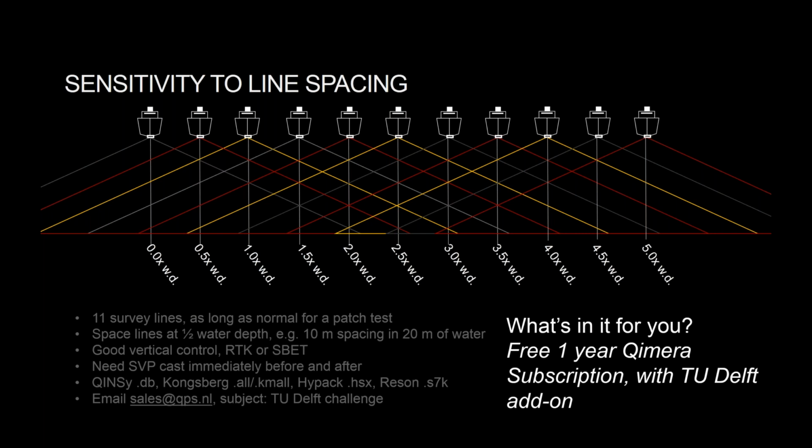Great. And so another question: does this tool still work in highly dynamic oceanographic conditions where things have changed from one survey line to the next? Yes, it's specifically designed for that. I've demonstrated it as a one-click wonder, and it seems to grab all the data and compute it at once. What's actually happening is we chunk it up. One of the parameters in the algorithm, I can't recall the name for it, is basically how many pings along track are used to solve for one instance of the sound speed for the center of that bundle of pings.